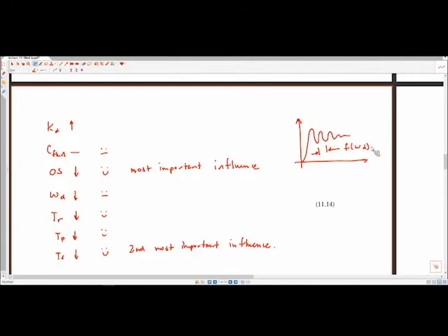Yes? What's the problem with raising the derivative term too high? There are some negative influences. So those of you who have actually implemented PID control on a system before, you may notice that if you increase it too high, you can accentuate noise in your system. And so, just kind of a side on that, we have sensors. We'll talk about sensors in a second here.